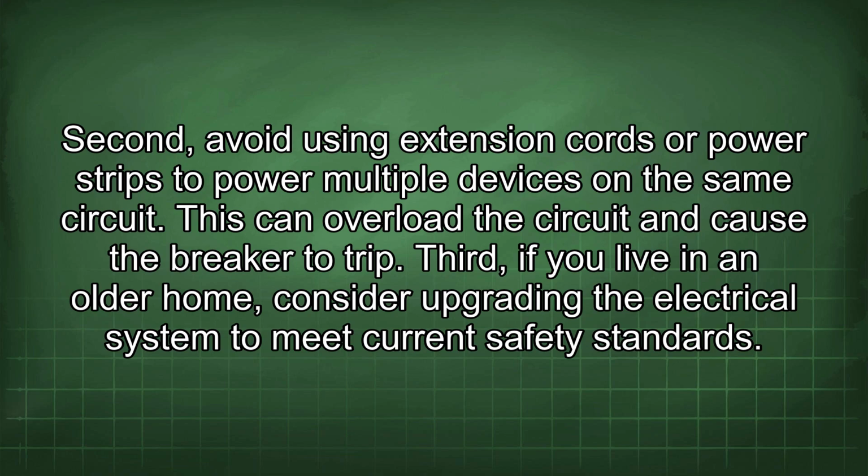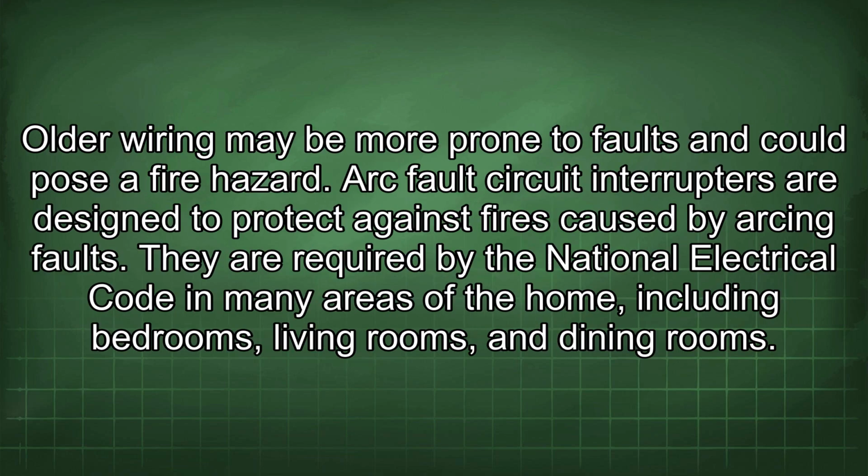Second, avoid using extension cords or power strips to power multiple devices on the same circuit. This can overload the circuit and cause the breaker to trip. Third, if you live in an older home, consider upgrading the electrical system to meet current safety standards. Older wiring may be more prone to faults and could pose a fire hazard.